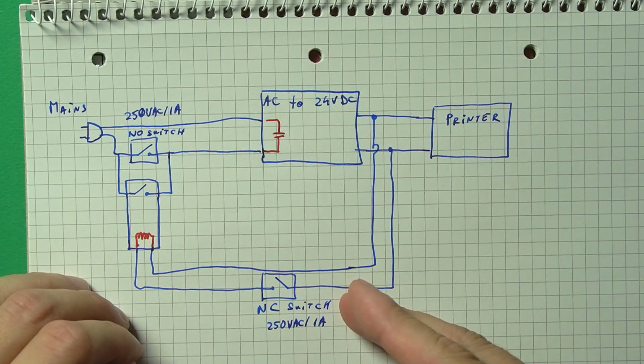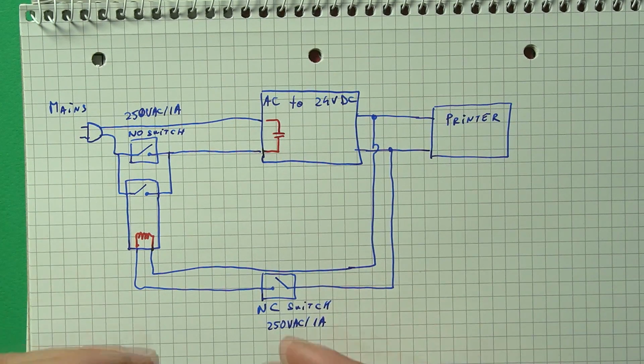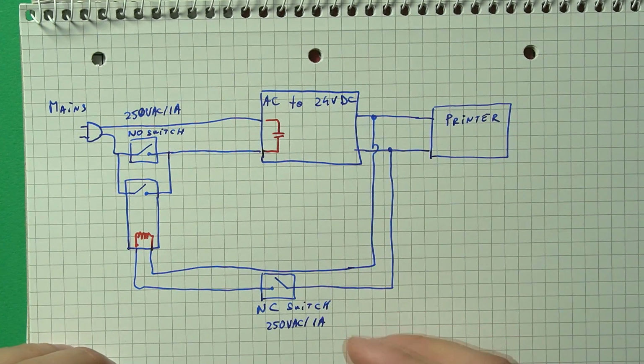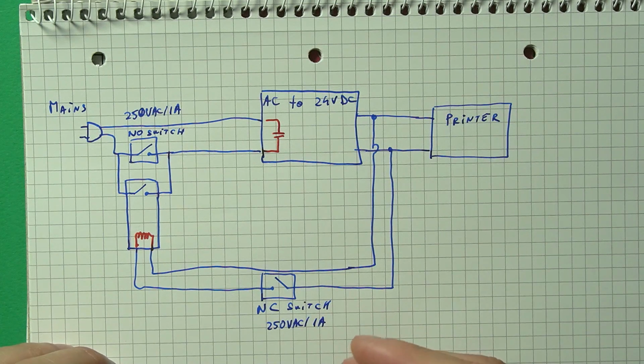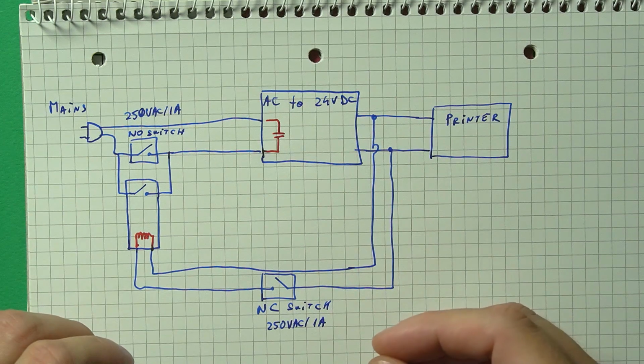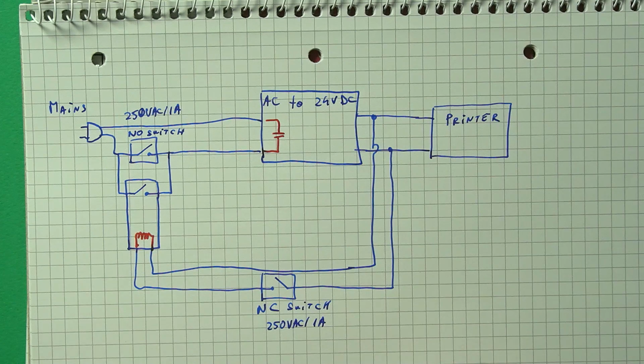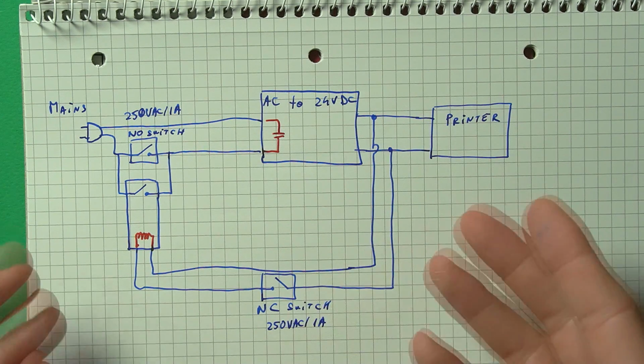The other switch is driving a clearly inductive load, a relay. It's a 50 milliamp or so circuit, but when the switch becomes open, all of the energy in the relay coil gets turned into a high voltage spike, larger than what the switch is rated for, and again the 250 volt 1 ampere switch ended up breaking.